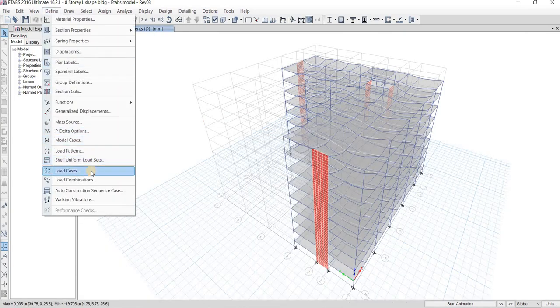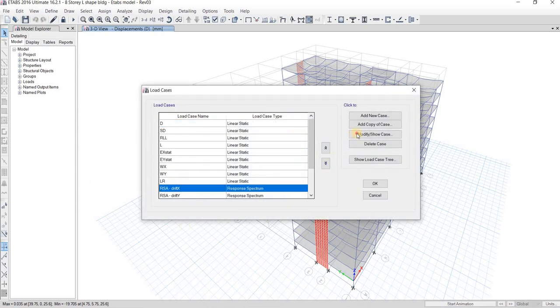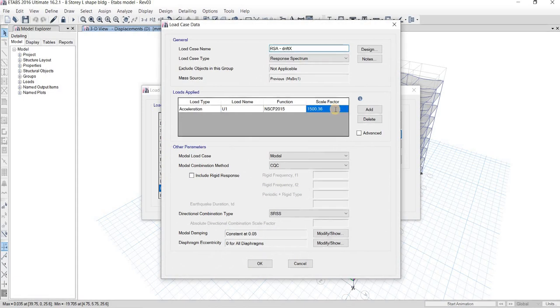but for this time, we already have a correct scale. So you will go here, load case, then you will click this drift X. Then to match that value, you have to multiply it by 0.83. Okay. Then you will run this one. But for now, we already have 100% scale.